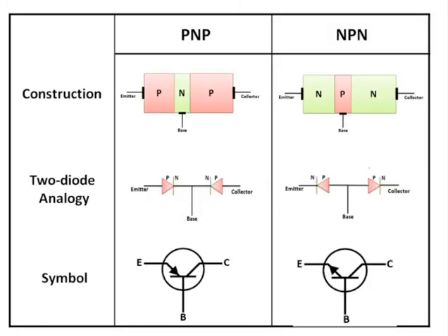Now we have already talked about NPN transistor. Similarly, you can apply all those things to PNP also, but everything is reversed. Here emitter is P type, base is N type, and collector is again P type. Here the diode connection similarity which is shown is also reversed, and the direction of this arrow is reversed here again. Now the current is flowing from emitter to base.